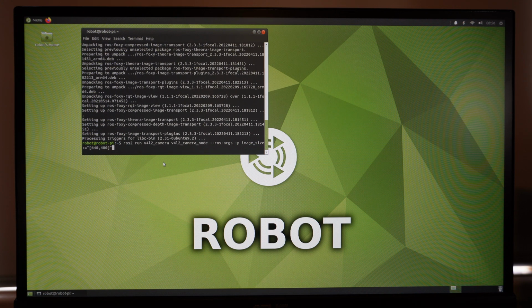And then we also want to set the transform frame that our camera is going to be in. So that's camera_frame_id. And you remember from before, we're going to set ours to camera_link_optical. So hit enter. That'll start up the driver node.